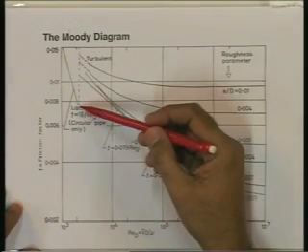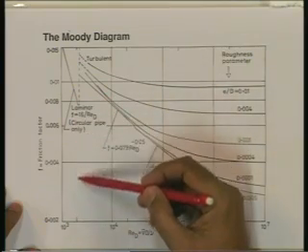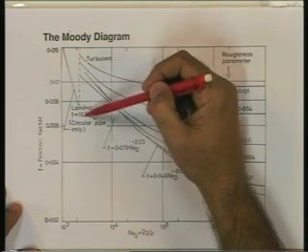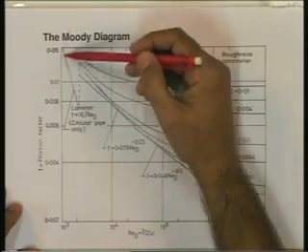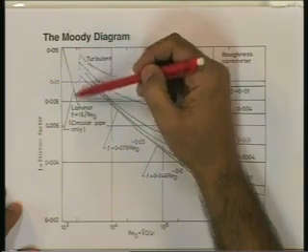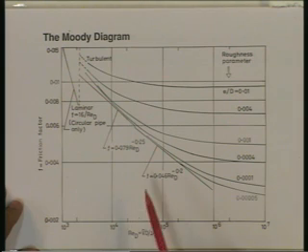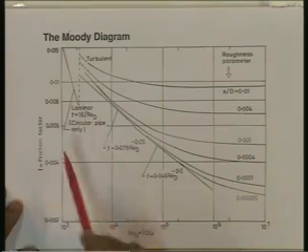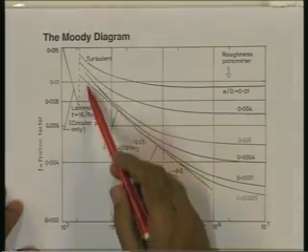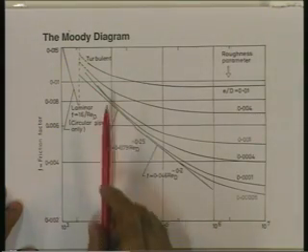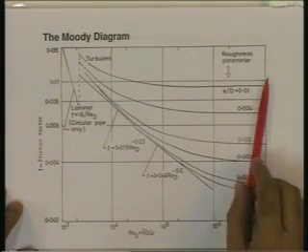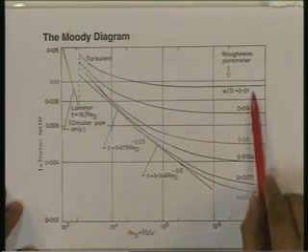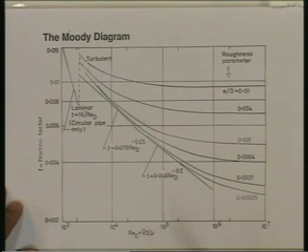Notice that when the flow is laminar, Reynolds number less than 2000, the laminar relation f equal to 16 by Re_d applies. That is represented by this straight line here. Beyond 2000, roughly till about 4000 or 5000 Reynolds number is the zone of transition, and beyond that we have the zone of turbulent flow, where the friction factor will be a function of Reynolds number as well as the roughness parameter.